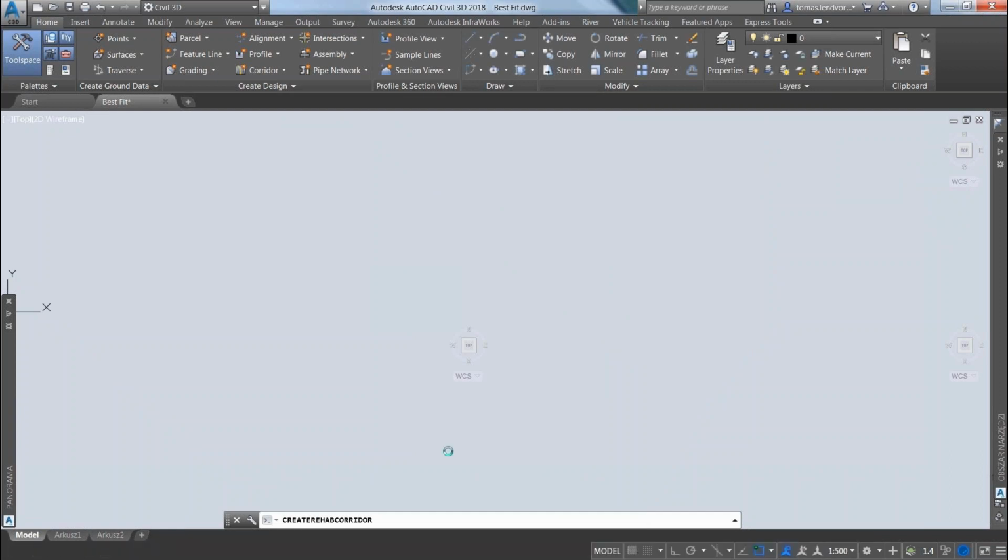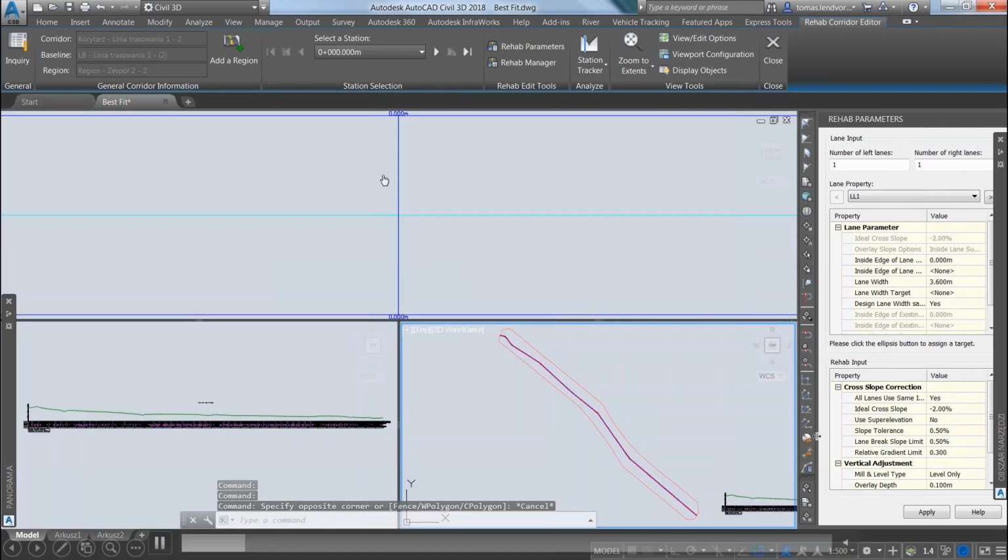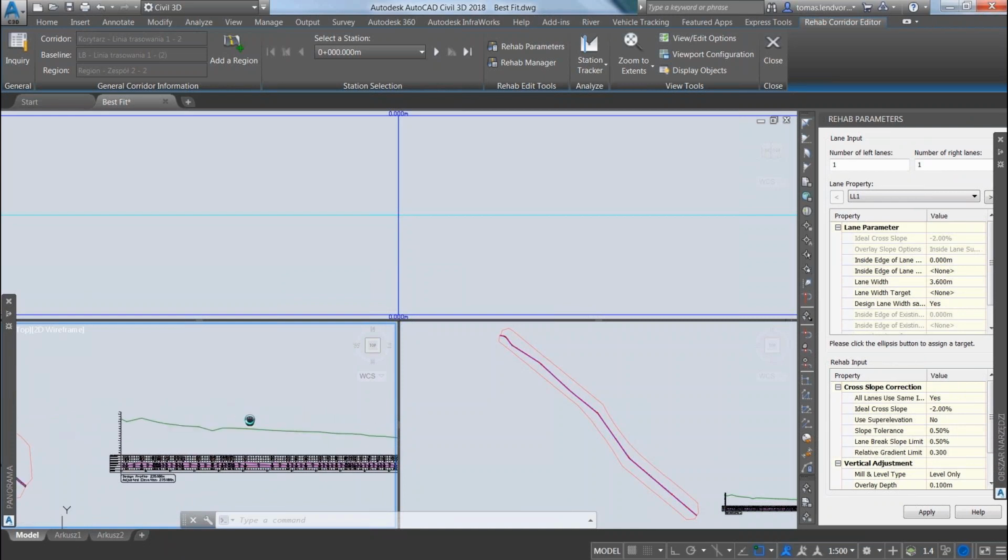So at this point, I didn't define some profile with parameters. And the system will automatically create 3 different views for me: cross-section view, which is empty at this point, longitudinal profile, and layout. Everything based on standard. Again, don't forget that Civil 3D is using what we call the template from Country Kit, and then everything is drawn according to this.